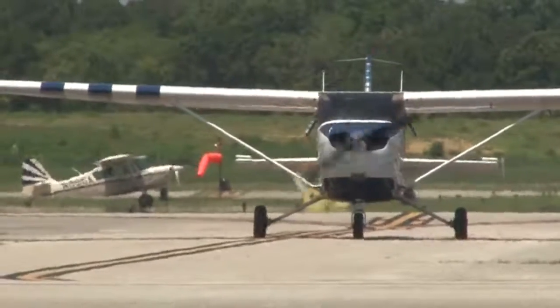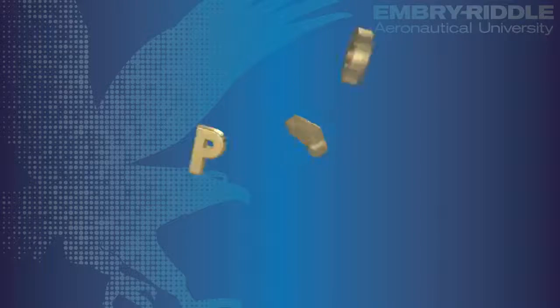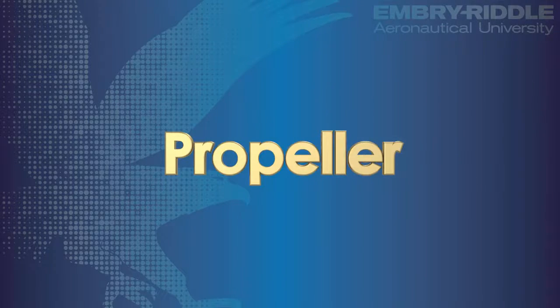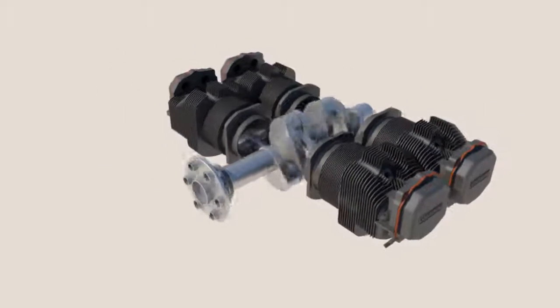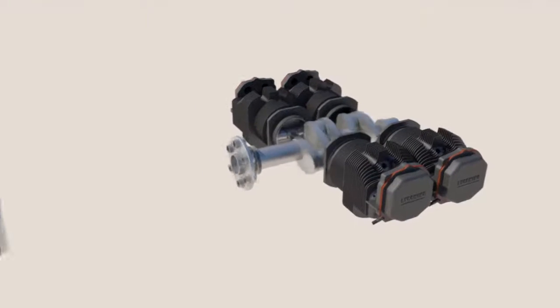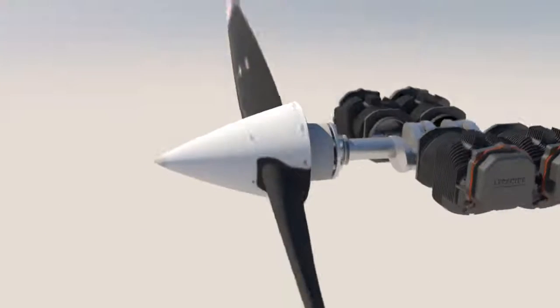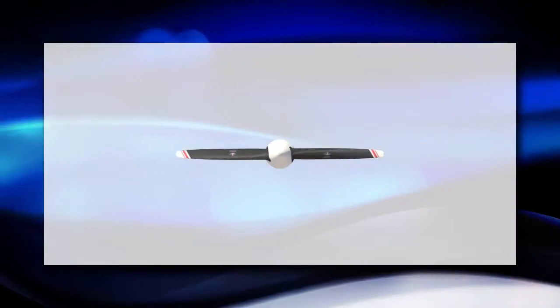Now that we have a better understanding of how an engine basically works, we will examine what creates the thrust for the airplane to fly. Remember that as the combustion occurs in the cylinder, the pistons rotate the crankshaft, which directly drives the propeller. The propeller, when closely examined, is actually twisted. This is simply to create equal thrust along the propeller blade.